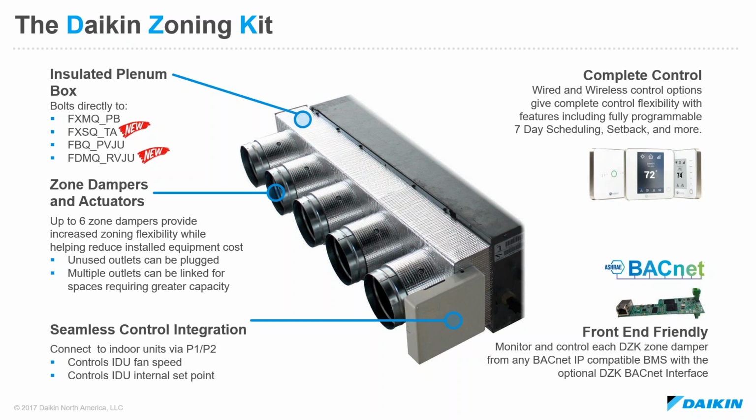And then we also have a BACnet IP card to allow us to start integrating the DZK into a BACnet IP front end. This is a huge advantage on light commercial projects where we want to be able to monitor and control each individual outlet and make commands and control the system.